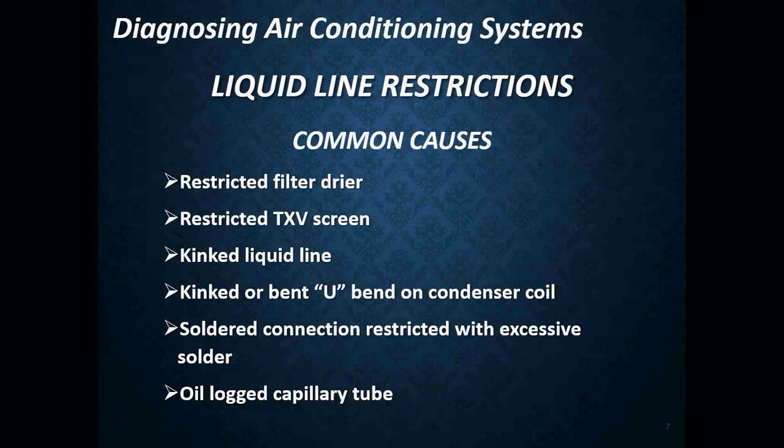Now, your liquid line restrictions. A lot of your common causes, if you have a problem with refrigerant flow, is probably going to be a restriction. That restriction can be in the liquid line. A lot of your common causes for that is obviously a restricted filter dryer, or a restricted thermostatic expansion valve screen. Some of your expansion valves have a screen in there that can get clogged up from dirt